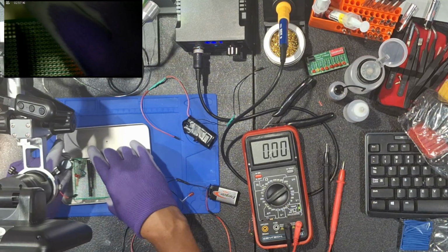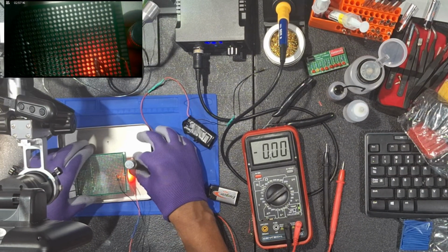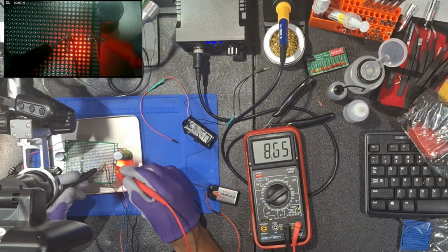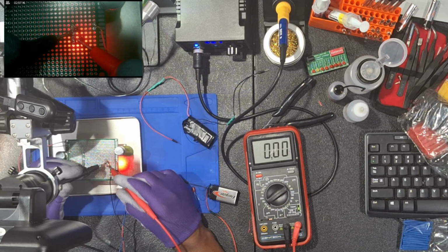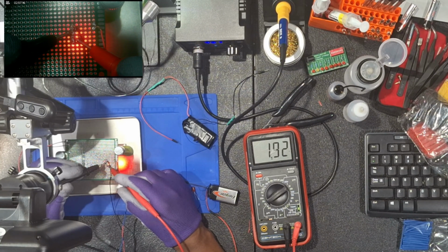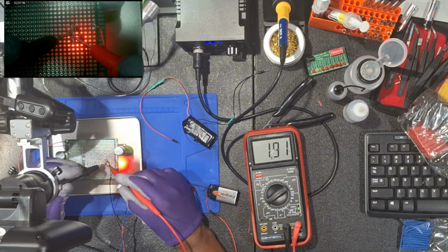So now I'm going to do a quick voltage test just to see the resistor in action. I'm going to check again how much voltage is coming from the battery and how much the LED is using. Testing the battery directly is giving me 8.6566 volts. And we already know that the LED cannot handle that much voltage. So now let's test the LED to see how much voltage is coming through behind the resistor. So the LED with the resistor right now is pulling 1.91 volts. And I remember before when I tested the LED without the resistor, I was getting like 2.85. So this right now is showing you that the resistor is working.